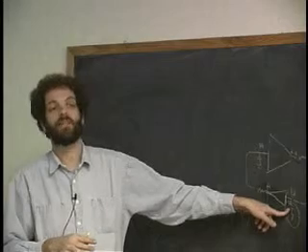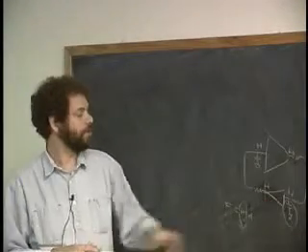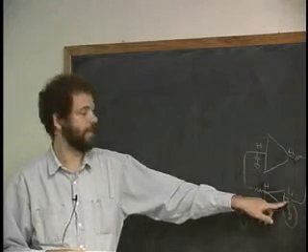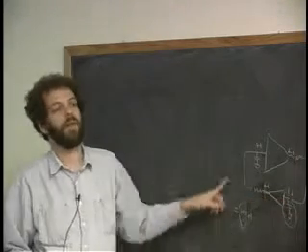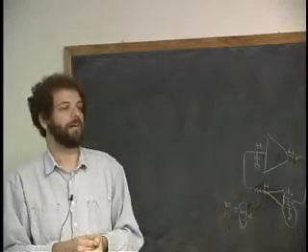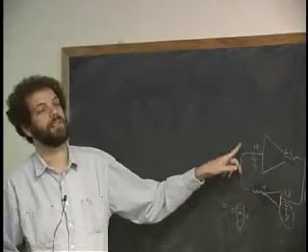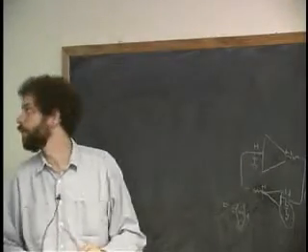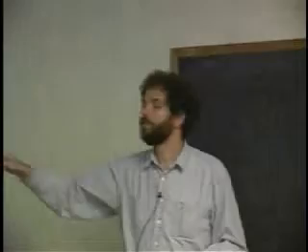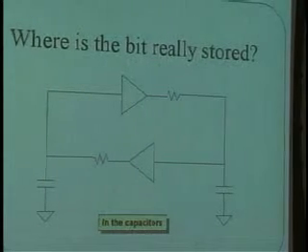And we said every thousandth of a second, the hardware needs to read out the value of the charge that's stored here in this little tub here, and then write it back with higher quality than what it read, because it can leak out after a little while. Circuits like this work exactly the same way, except the refresh is happening continuously, all of the time. So all of the time, those two capacitors there are being read, having their quality improved, and being written over and over and over again.